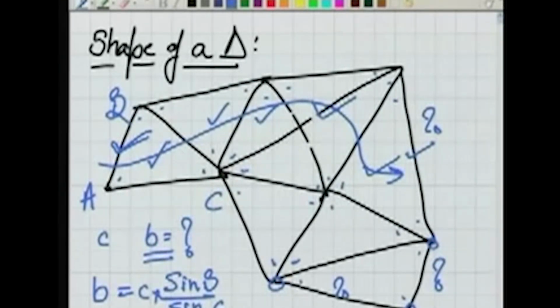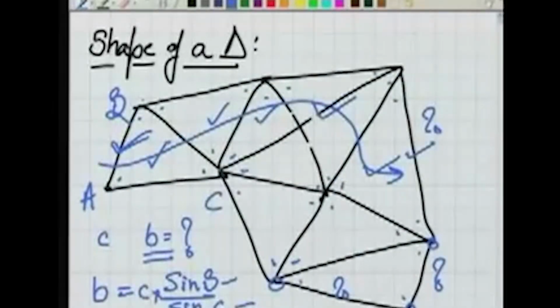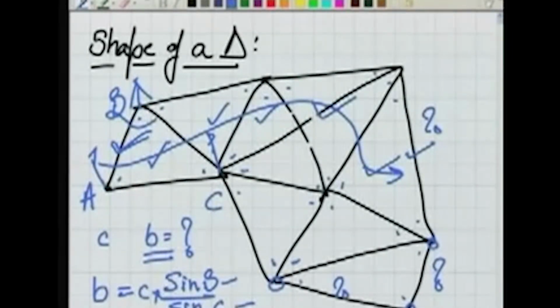So if there is an error in angle B and C, which there is, we know because we have measured these angles in the field, and once we are measuring the angle in the field, we are making use of the theodolite. What do we do? We bisect the target. For example, to measure angle at B, we are bisecting the ranging rod at A and the ranging rod at C. I am saying ranging rod, it could be the signal, the big tripod signal which we will see later on. So by doing that, we are measuring angle ABC.